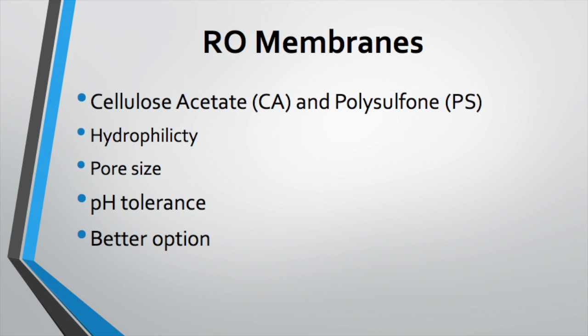Reverse osmosis has the ability to utilize over 10 different types of membranes, each with unique features. 2 different types of membranes are cellulose acetate membranes, or CA membranes, and modified polysulfone membranes, or PS membranes. CA was the first membrane material used for RO, and is still used in present-day RO plants, while PS is a more modern development and is widely used in current plants.